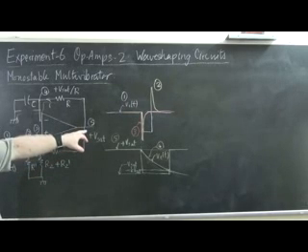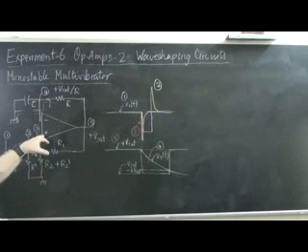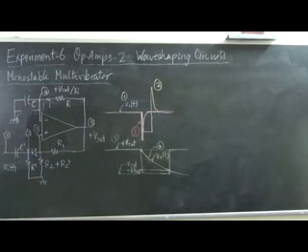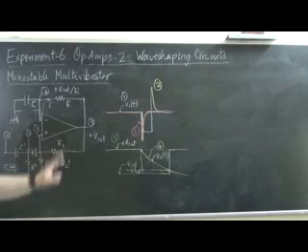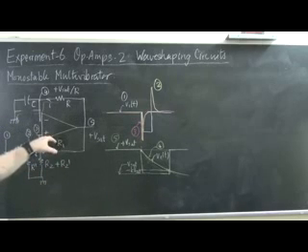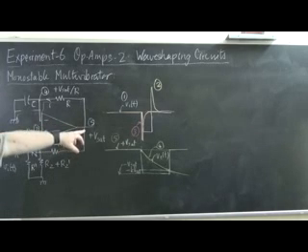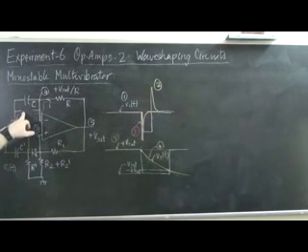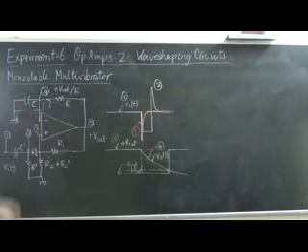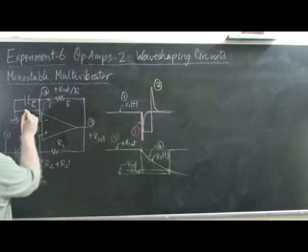Now when it transitions to minus Vsat, here we have minus k Vsat as the new non-inverting terminal voltage. The pulse in the meantime has come and gone, so we have minus k Vsat over here. And with the inversion of this to minus k Vsat, the diode is now reverse biased and open, and is therefore eliminated from the circuit for better understanding.